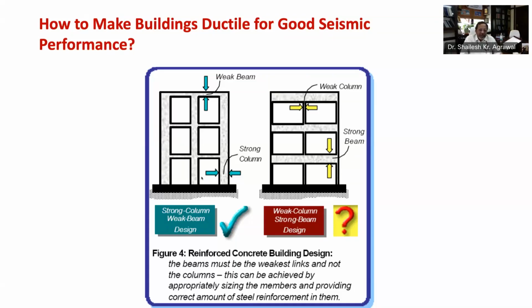Therefore, strict enforcement of prescribed standards for construction materials and construction processes is essential in ensuring an earthquake-resistant building. Regular testing of materials on site and at laboratories, periodic training of workforce, and on-site evaluation of construction work are elements of good quality control and must be adhered to for earthquake-resistant construction.